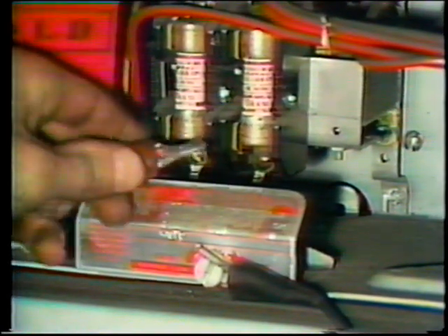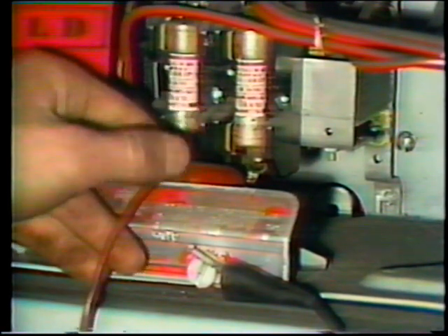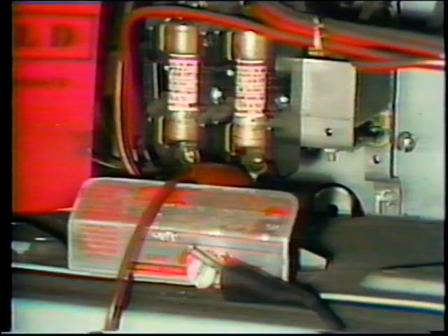Next, he removes the probe from the fuse and connects it to the output of the second fuse. This will give him a reading from the second fuse to the other side of the start switch. A reading is taken and shows that there is high resistance. A ground does not exist in this part of the circuit.